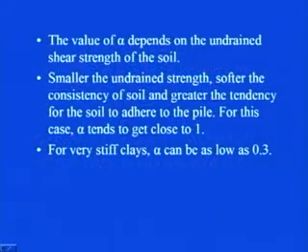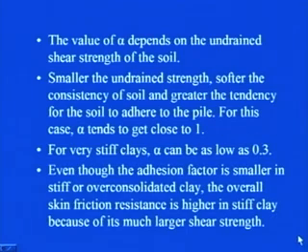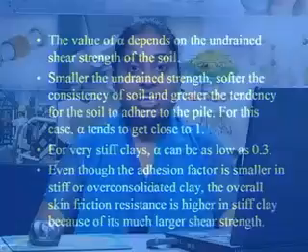For very stiff clays, this alpha can be as low as 0.3. Even though the adhesion factor is smaller in stiff or over consolidated clay, the overall skin friction resistance is higher in stiff clay because of its much larger shear strength, because you know that it is alpha times Cu. So, although the value of alpha is small, Cu being more in case of over consolidated or very dense clay, the skin friction resistance is higher.